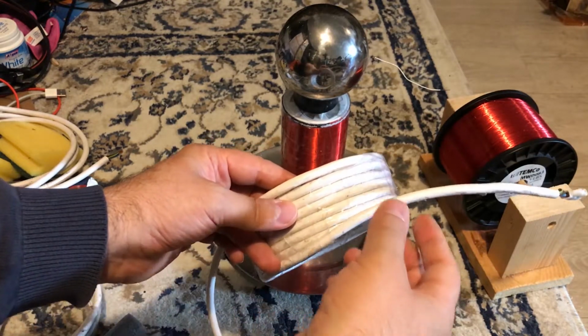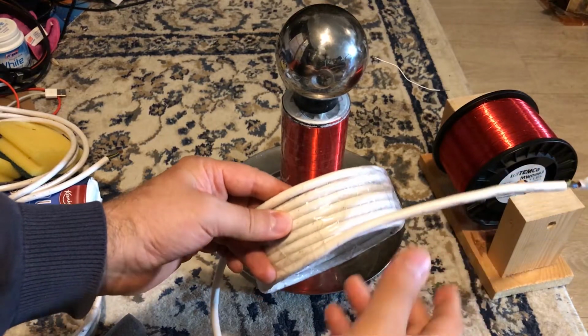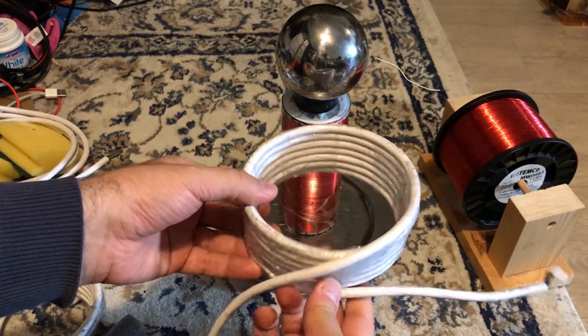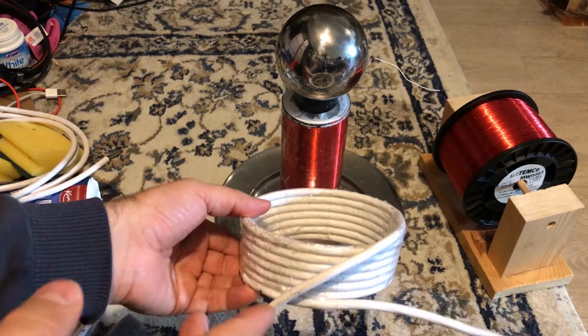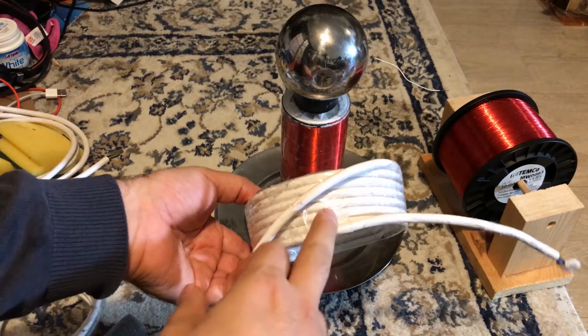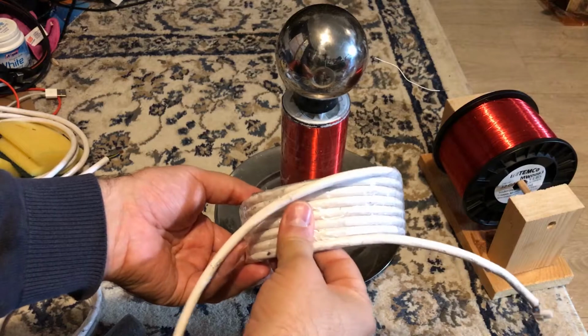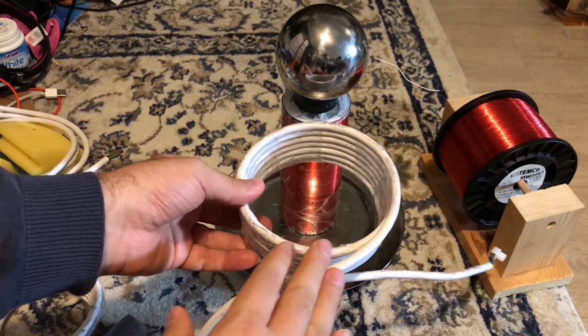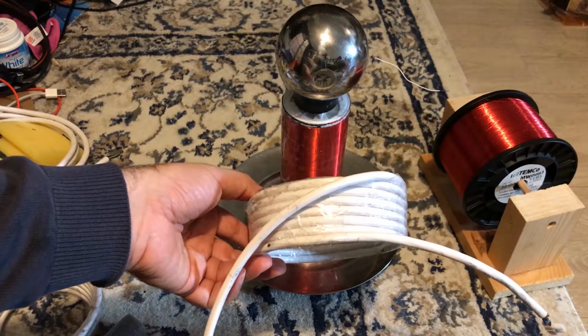Now in this case we use wire with insulation around it, so we do not have that option. So if you want to tune the primary circuit to the secondary circuit, we have to change the primary capacitance. Of course, changing the number of turns is much easier and cheaper, but in this case it was very easy to construct this primary winding, and tuning the capacitance will not be very difficult either.